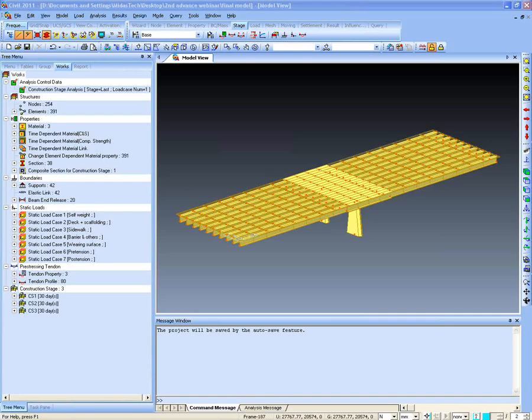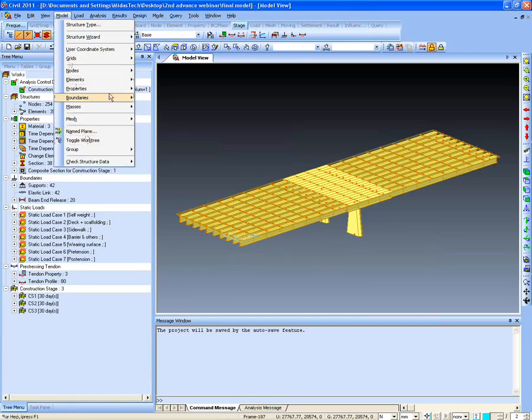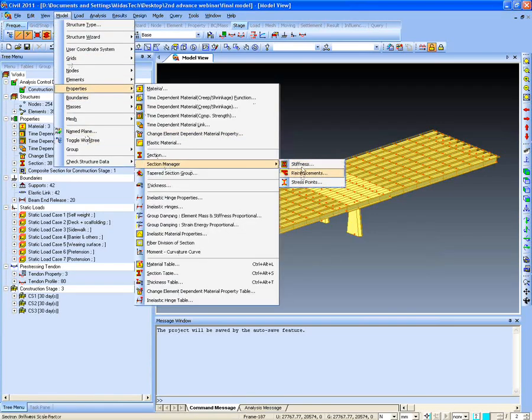There is a question by Mr. Eddie, that he wants to do the FRP strengthening of the beam and how he can model it in MIDAS Civil. So as I told you in my presentation, you can use the section stiffness scale factor.